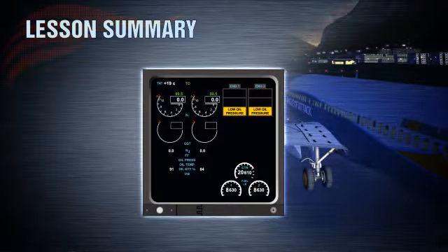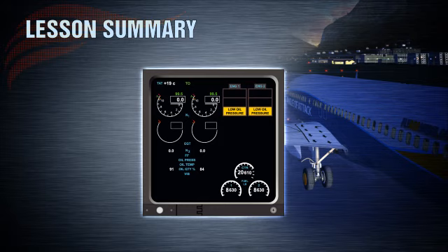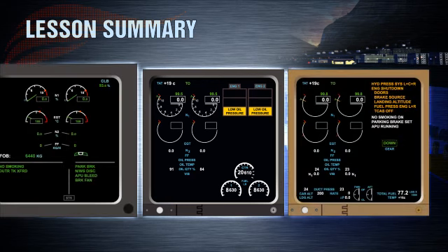There are many hundreds of controls and indications on the 737 Next Generation flight deck. The master caution system on the NG has changed little, aesthetically at least, since those installed in the original 737s of the 1960s. It is considerably behind modern systems such as ICAS and ECAM, but nonetheless it does an effective job of directing crew attention to problem areas and should be intimately understood.